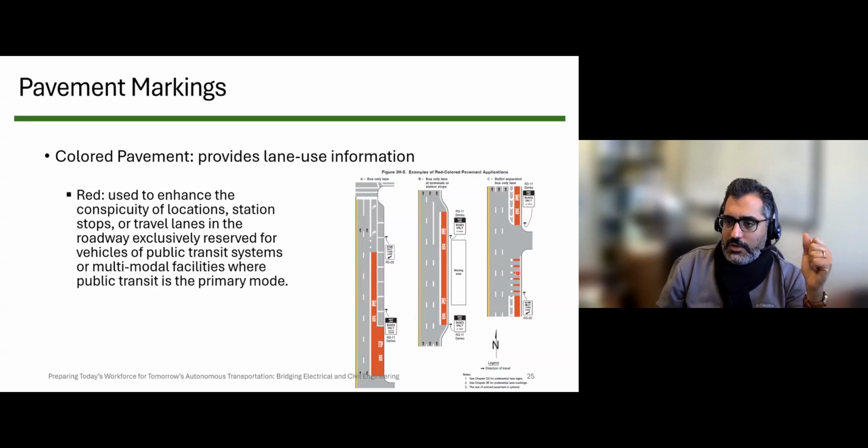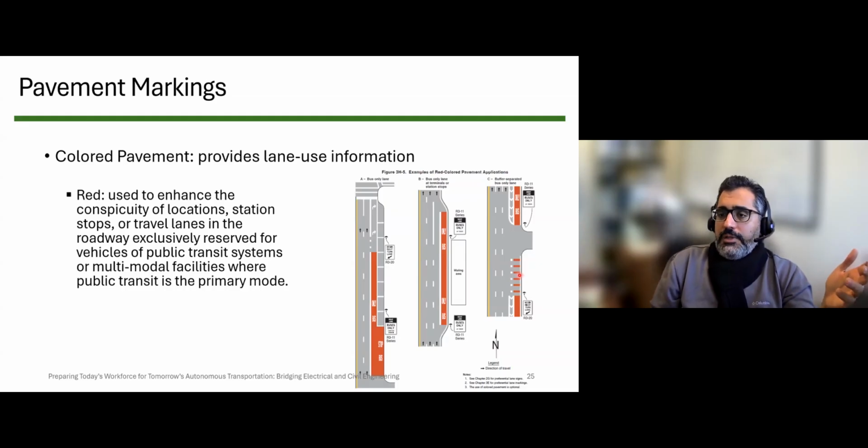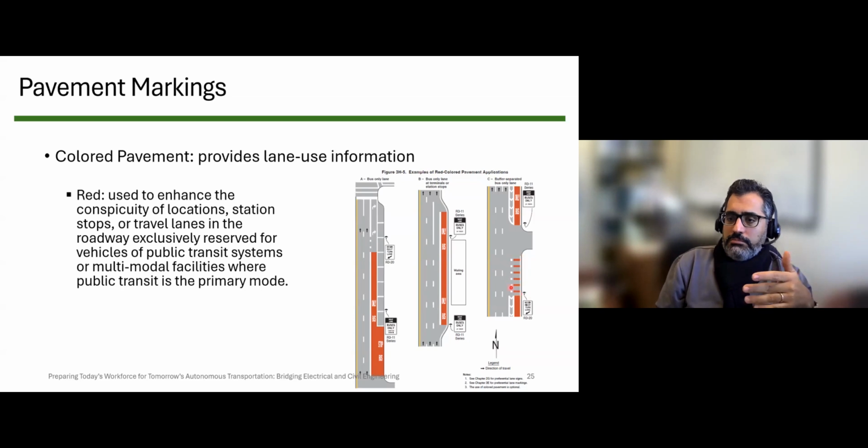Look at this again. When we have some sort of conflicts, interactions between mixed modes happening, we have this dashed pavement marking. Although you should know that this is not universal. Even within the United States, there could be different applications. There could be nothing on the roadway. There could be just longitudinal white pavement markings without any color applied. So these are mostly suggestions.